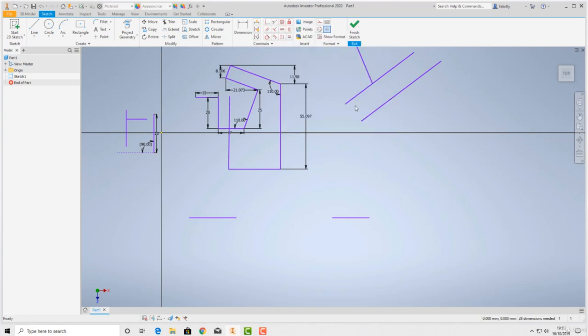Concentric constraint. Concentric's a word you'll see in Inventor. It basically means, it's used with circles. So the concentric point is the center. Maybe you have another circle here. You think, whoops, the smaller circle should lie in the middle of the big circle. Okay, so there, we click them both. They're now concentric. The center points are in the same place, basically.